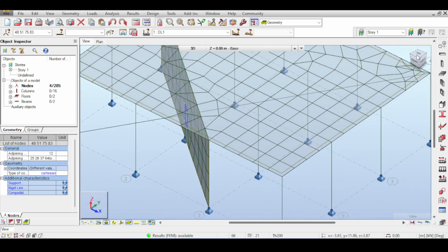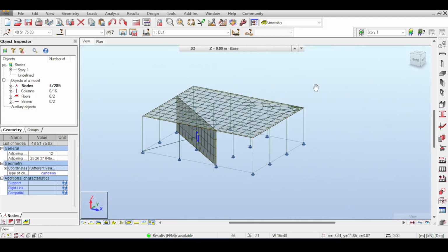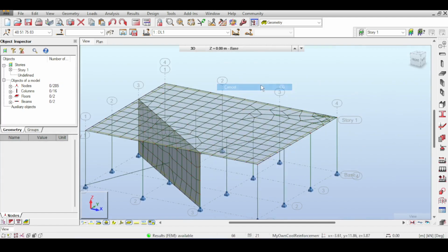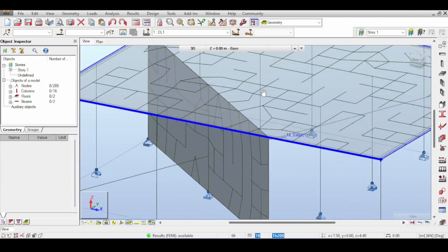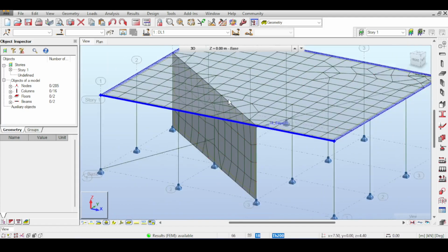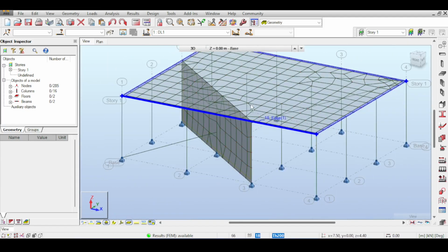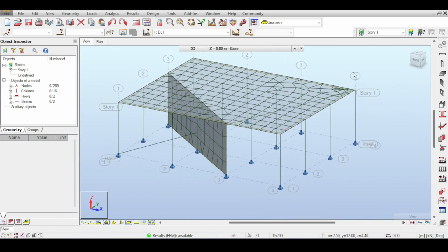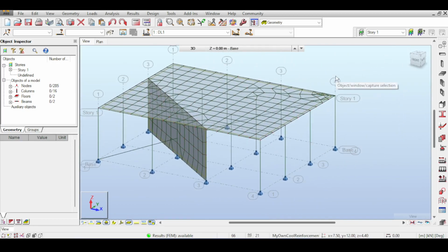So what I'm trying to say is that a mesh in a finite element software is basically the skeleton upon which you are moving the forces. If you have two things connected in a mesh at a node, this means that they can see each other and feel each other. If you don't have that, then they don't see each other, don't feel each other, don't even care about each other. It's very important that you do have a consistent mesh.